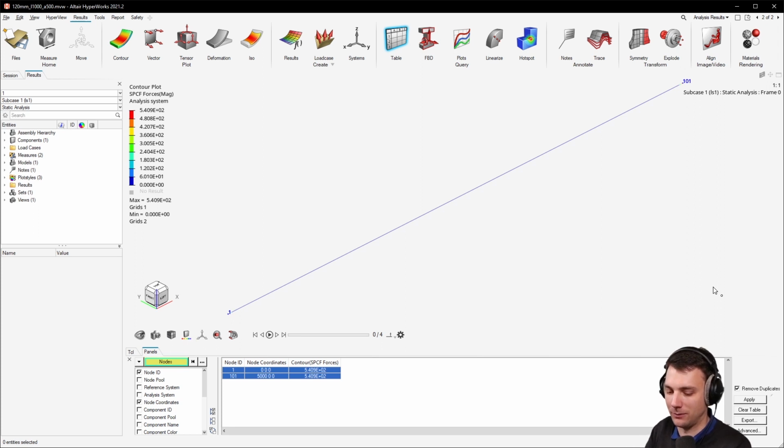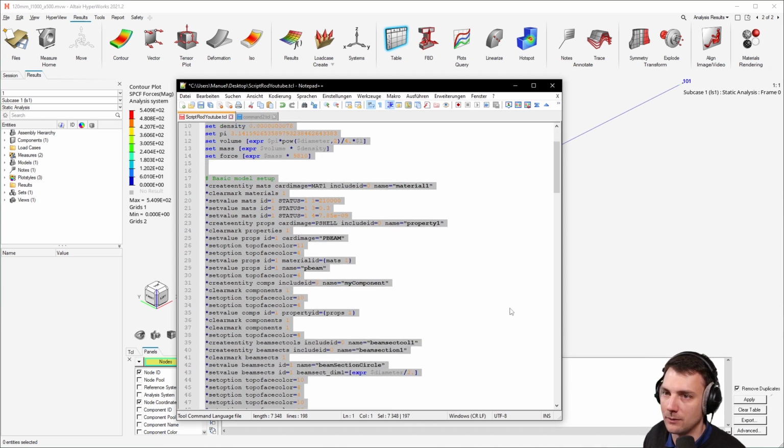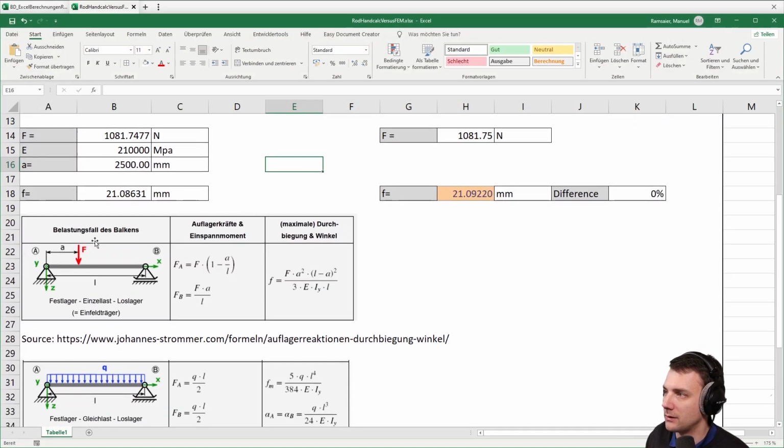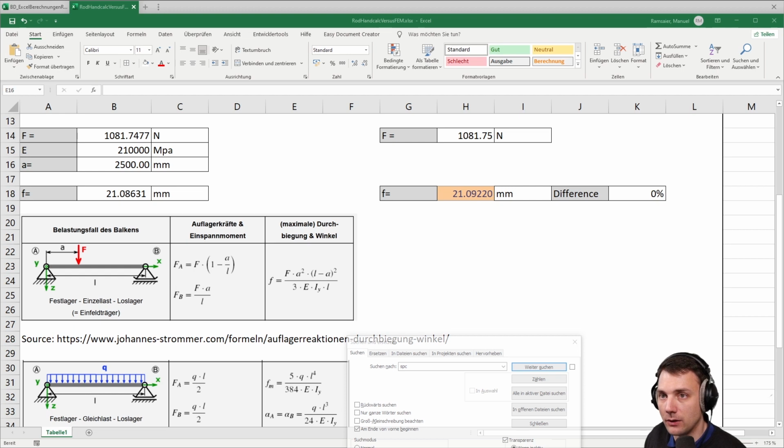So to recap, what we did here was we created a routine for creation of different setups for problems like these. So we have a bar with two bearings which do not support the moment, but just translational is fixed. And we can also change where the force is acting. We can change the mesh size. Right now the force is defined as the self weight, but this could change. You can put into the force whatever you would like as a parameter here, and everything else beneath runs smoothly. And again, you can change model sizes and mesh sizes and compare it.